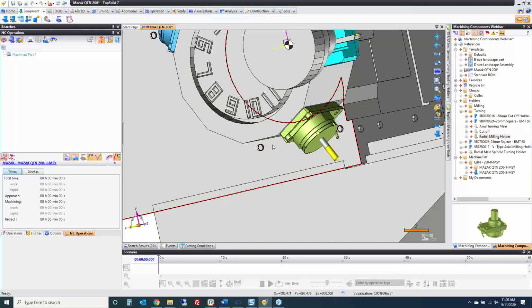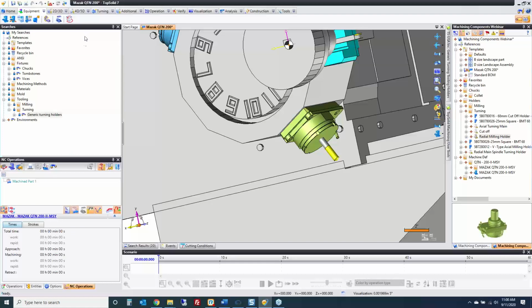Now, looks like we're coming to the end of our 1/2 hour. I just figured I would show one more quick thing just to kind of give you guys ideas, and this is more that will be taught in that class I spoke about. As far as using components efficiently, you want to put them in a library. Okay, test them first, make sure they're right, then throw them in a library. And then to make the deployment of them even faster, you can create saved searches.